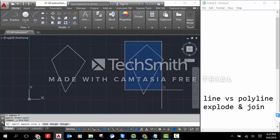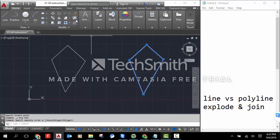If I come over here to the other side and I hit the explode button, it will now recognize it as individual pieces. This is helpful for whenever you have things stuck in a group and you need to explode them, you use explode. And if you want to bring the shape back together, you just join. I'm just typing in J-O-I-N.